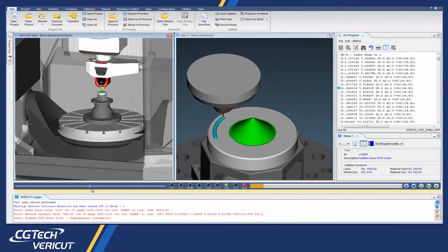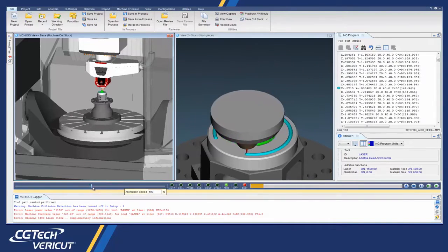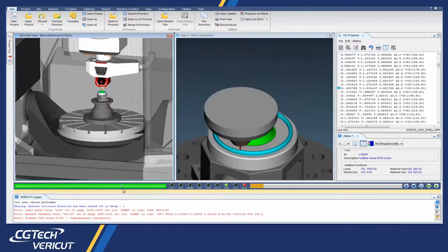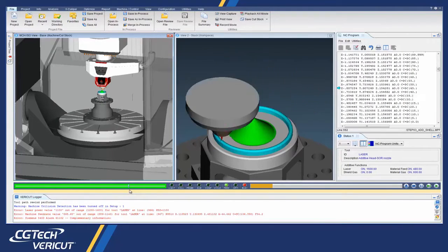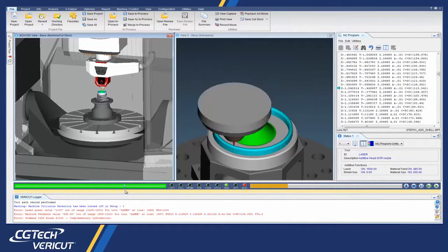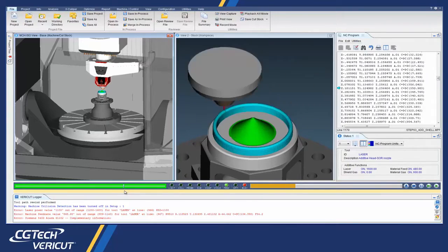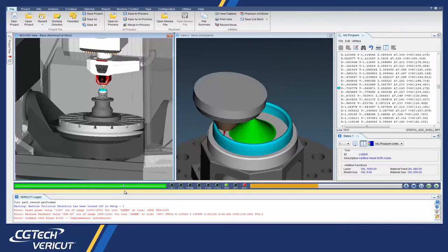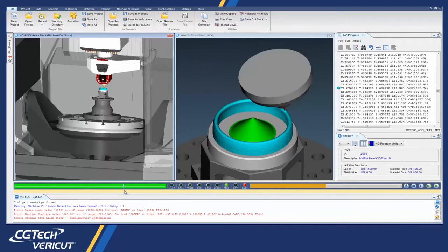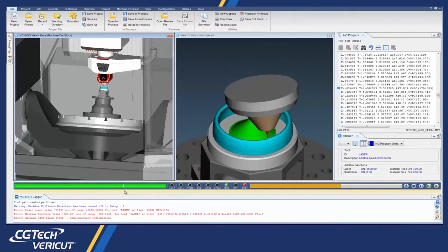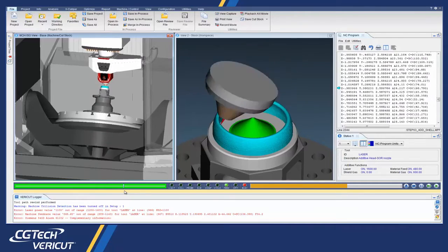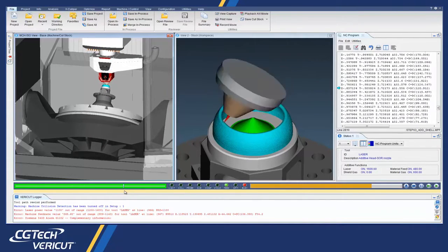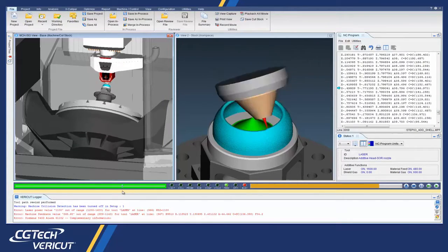This additive capability checks accurate laser cladding and material deposition, detects collision between the machine and the additive part, and finds errors, voids, and misplaced material. For the highest accuracy, Vericut simulates the post-processed NC code that will be used to drive the CNC machine and ensures proper usage of additive manufacturing functions and laser parameters.